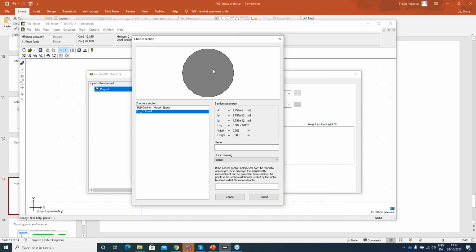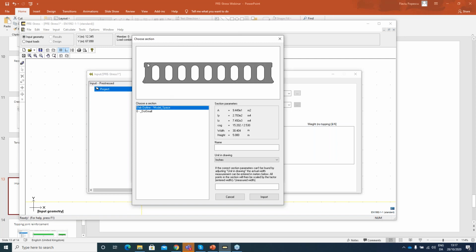This is the algorithm looking for closed lines and continuous lines. So it will automatically detect enclosed surfaces and polylines. So you need to make sure that your profile is well defined from the drawing. Also make sure that you have a continuous line and closed regions for the cores in the profile.